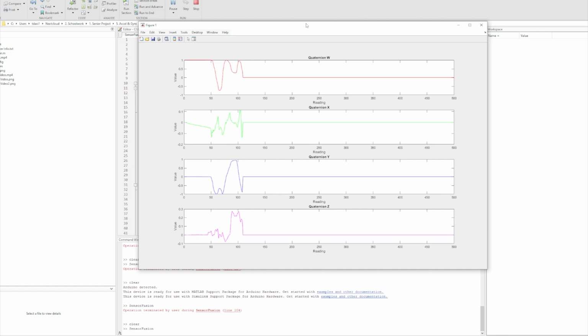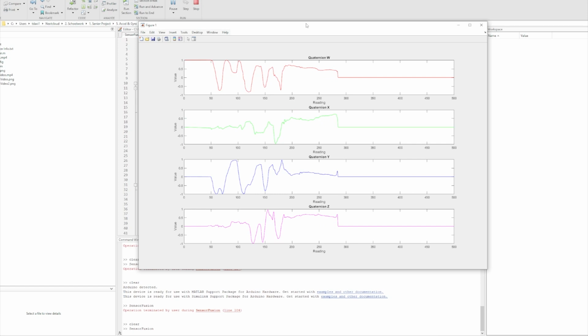Quaternions combined with advanced filtering offer smoother and more accurate orientation tracking. While Euler angles are helpful for simple rotations, they struggle with complex 3D movements. Quaternions, especially with the Madgwick filter, excel in dynamic environments, making them the better choice for real-world applications.